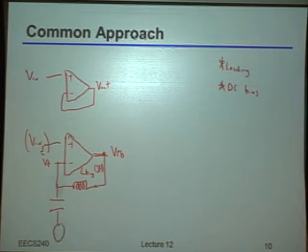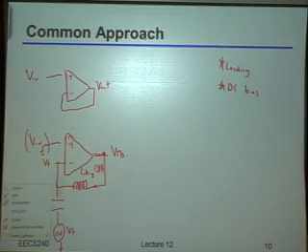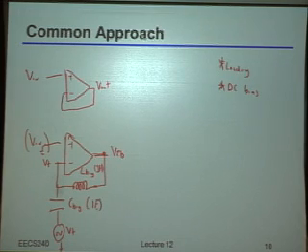So just to be clear, I put my voltage source here like this. Where again, the whole trick here is that I don't want to mess up the DC biasing, so I can't just drive the voltage source directly. Instead, I'll put a cap in between, and that cap is, of course, big. So just an example, let's say 1 farad or something like that. I put the cap in to make sure that, once I've gone away from DC, I can actually apply that test source directly into the input.